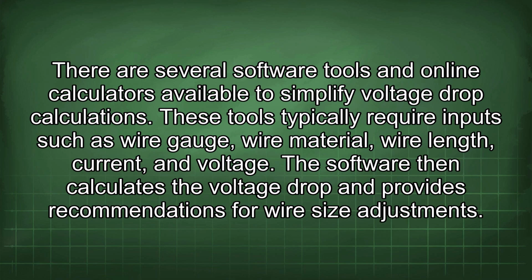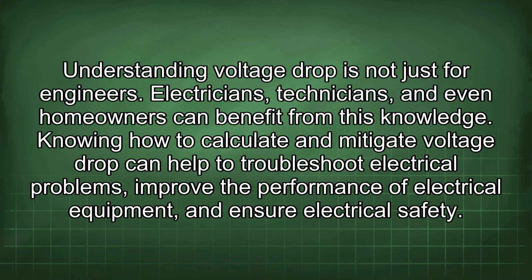There are several software tools and online calculators available to simplify voltage drop calculations. These tools typically require inputs such as wire gauge, wire material, wire length, current, and voltage. The software then calculates the voltage drop and provides recommendations for wire size adjustments. Understanding voltage drop is not just for engineers. Electricians, technicians, and even homeowners can benefit from this knowledge. Knowing how to calculate and mitigate voltage drop can help to troubleshoot electrical problems, improve the performance of electrical equipment,